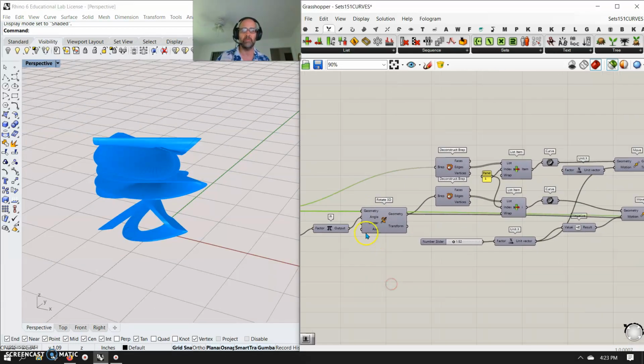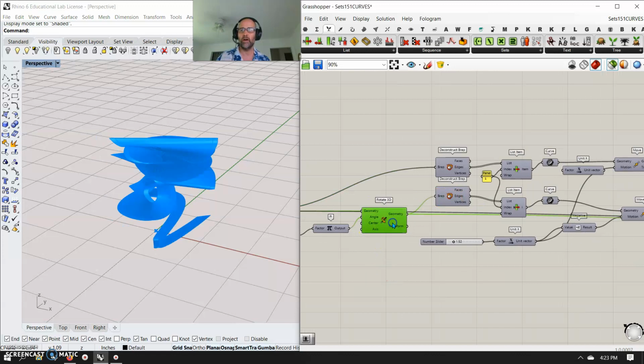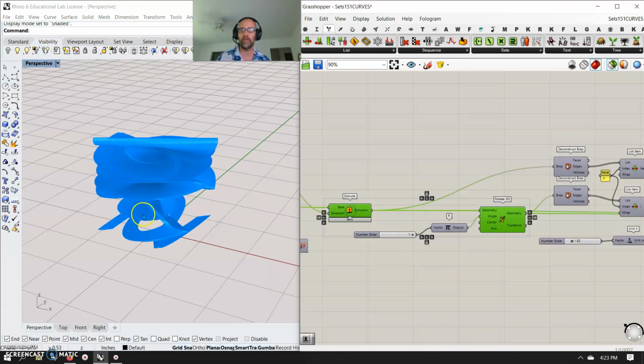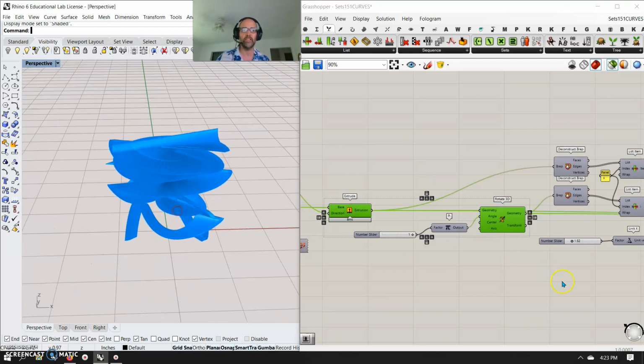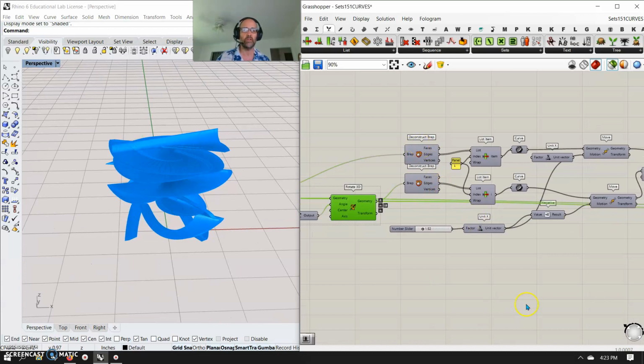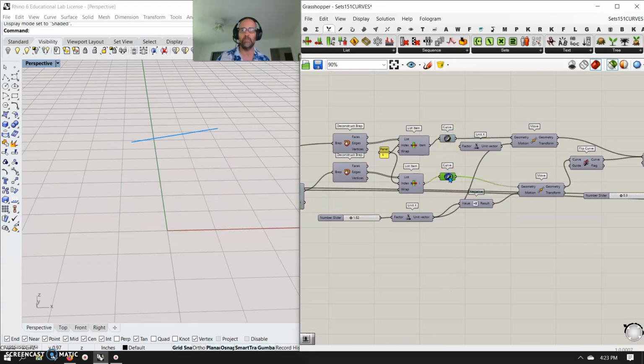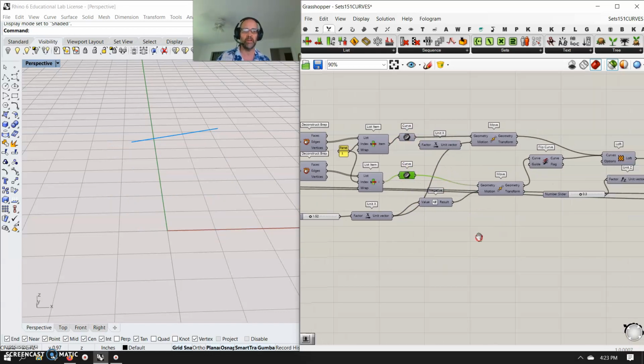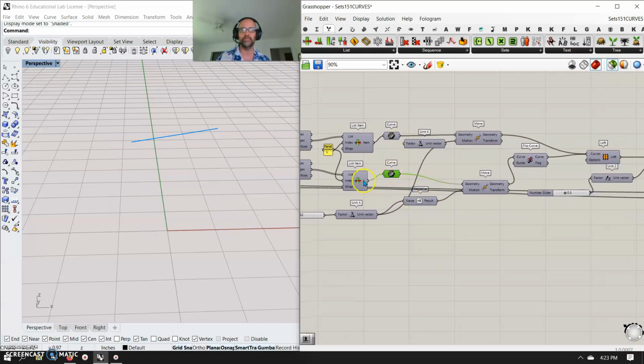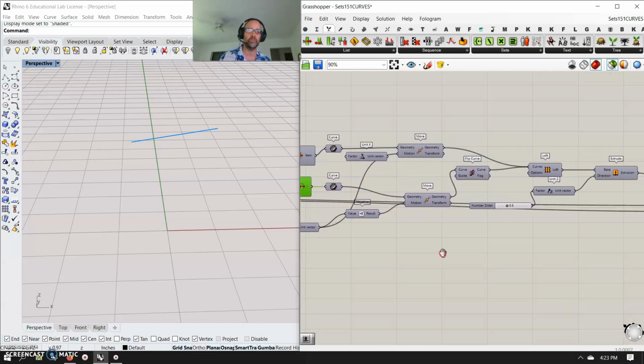Now, all I did past that was do a quick little rotation on it so I could have this copy and this copy, because that would balance it out and give it 2 legs. And once I deconstruct the breps there and pull the curves, I can pull the top line. Didn't have to pull them both, but I did. I could have used the same line for both. It's kind of ridiculous that I did that. I wouldn't have to find this list item in the other one unless it comes up different for some reason when I change the script. So if it's working and I've done extra work, I'll leave it until it goes bust.